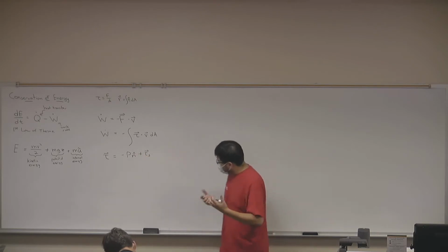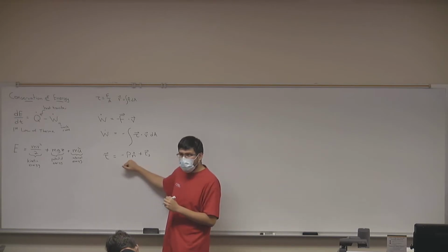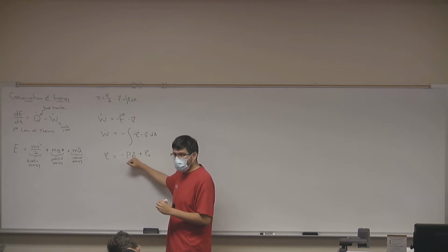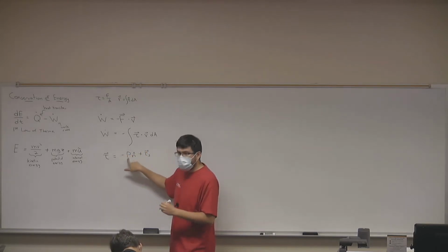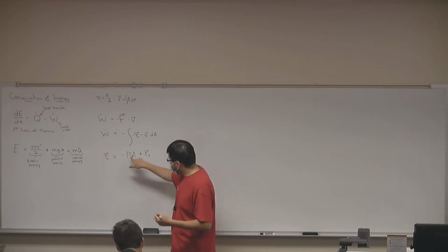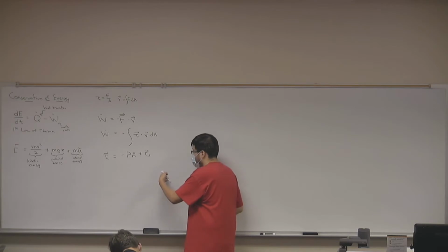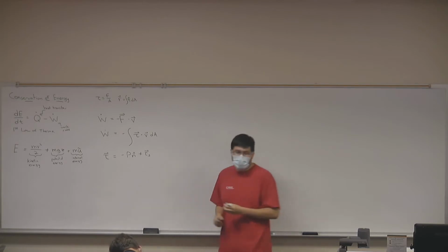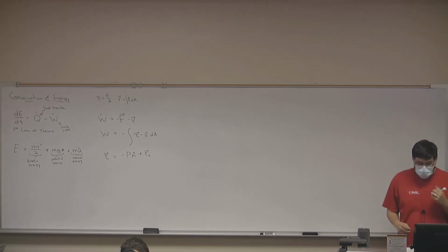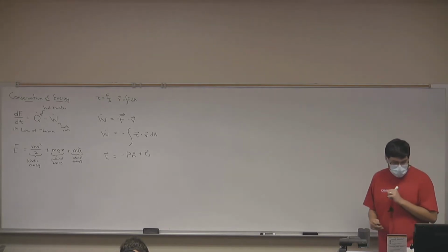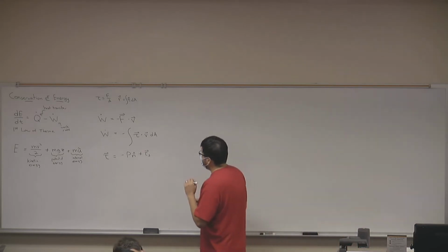Remember, well, I haven't told you, but I always tell my statics students to always visualize vectors as products of scalars and directions. So my normal stress is a product of a scalar, that's the pressure, that's the magnitude, times a direction of the pressure. So this n hat is a unit vector normal to my area. And you'll see why this unit vector normal to my area is important in just a second. So what does this tell me about my work rate?